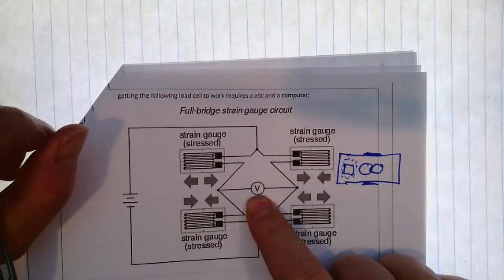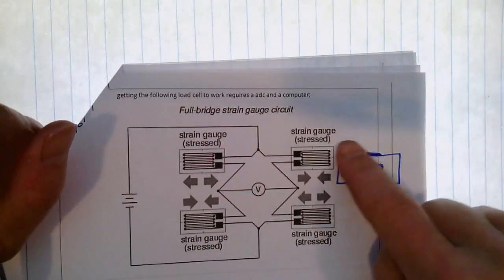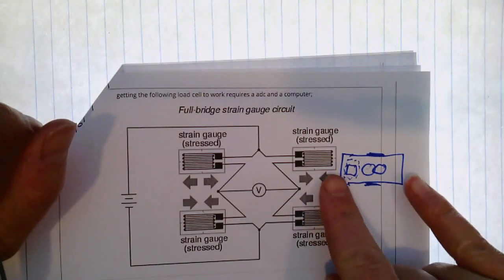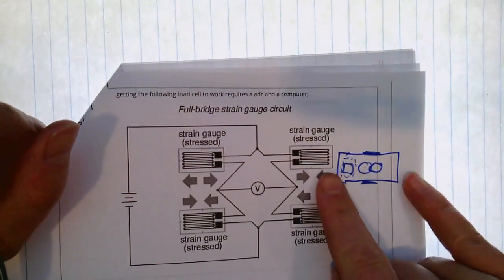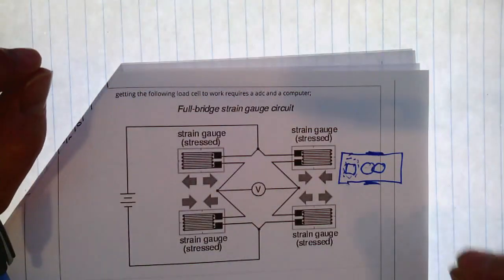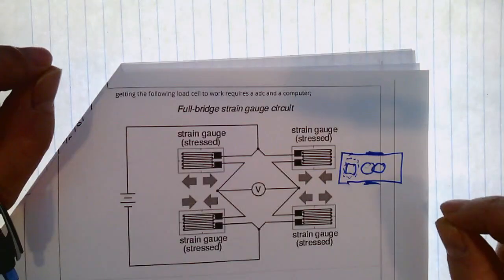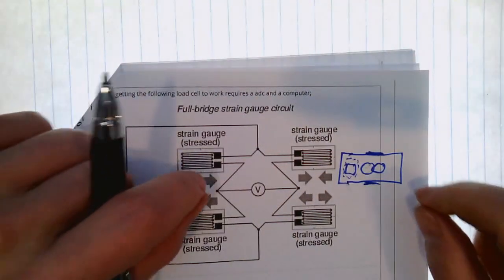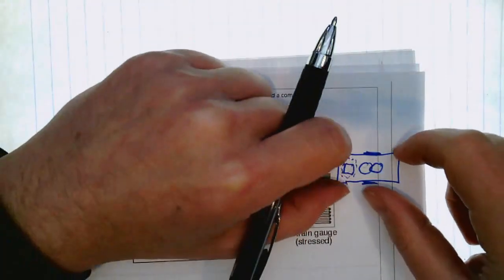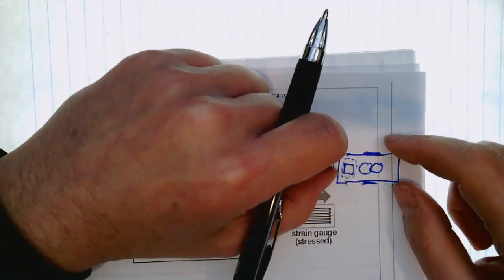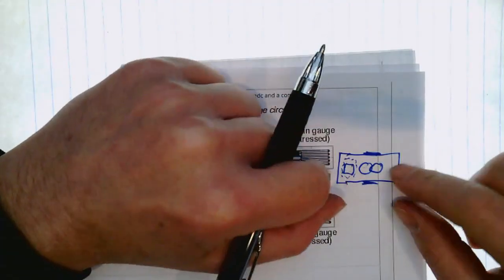This voltmeter will measure the difference between the two, so you'll see how much something is stressed. And if you have this bar calibrated as a material property so that it will be in its elastic mode, then as it bends, it will go back into its original shape. That's what it means to have an elastic material. If you bend it and it stays bent, then you have had what's called plastic deformation. The point at which you bend it and it no longer returns to the original shape is known as the yield strength of the material.